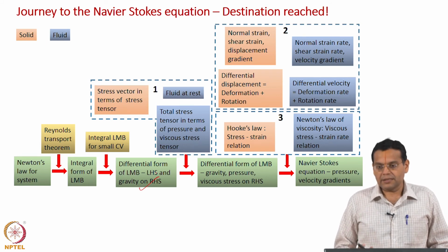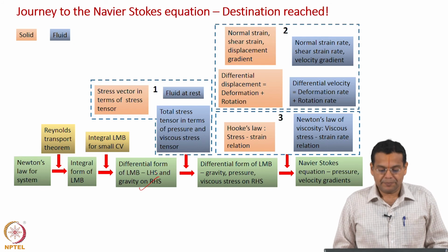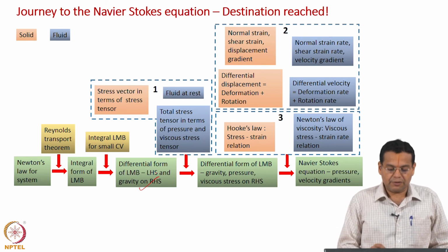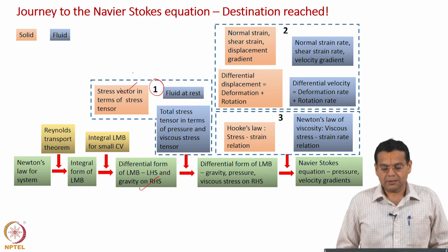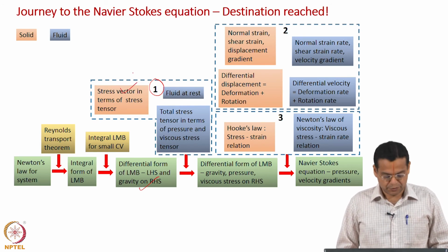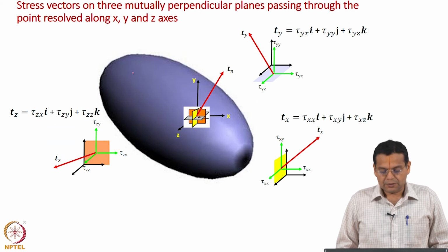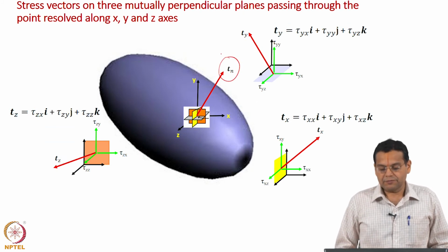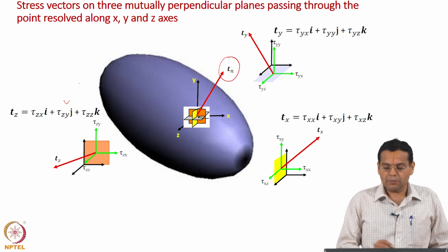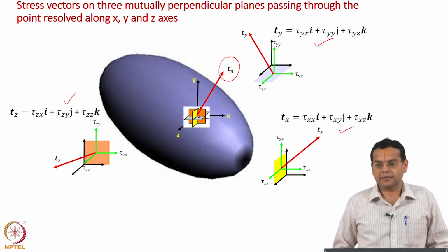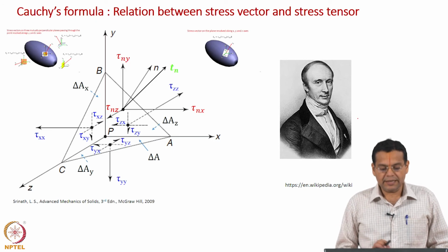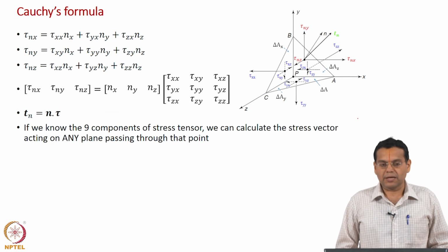We need to understand the surface forces, we need to express them. For that we took our first diversion to solid mechanics, where we discussed this block, stress vector and stress tensor. So, a few slides from there. The stress vector and the components of the stress tensor. Then we related these two, the stress vector to the components of the stress tensor, using Cauchy's formula.